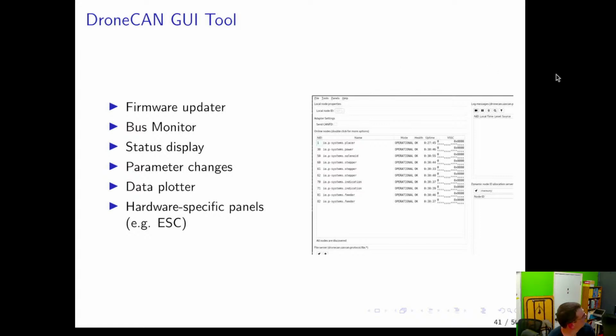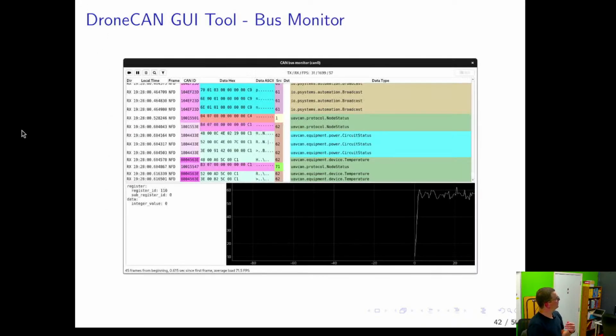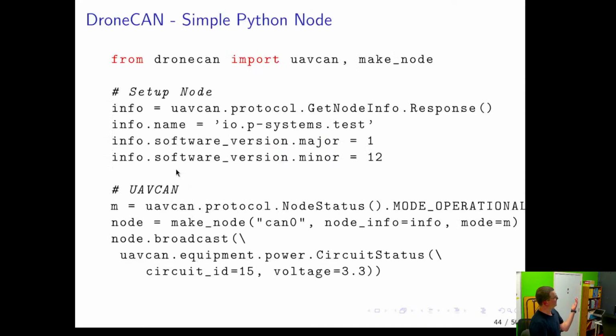So if you had a front camera and rear camera, front LiDAR and rear LiDAR, you'd use the source ID to differentiate? No, because they'd have the same message type. If you had different sensors sending the same message, the message itself needs to have something to differentiate them, if you want to know that they're different. Sometimes maybe you don't care. With a GPS there's only one, but with two power sensors, one would have to have an identifier.